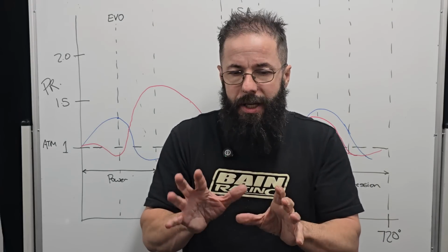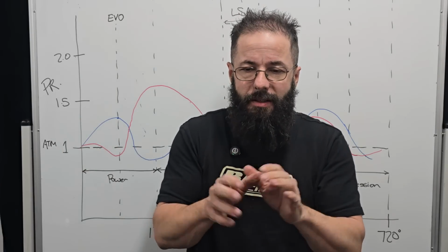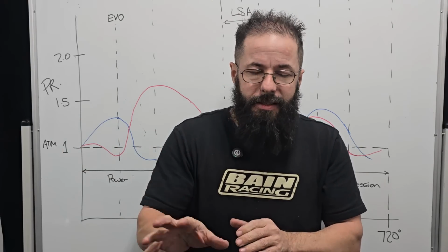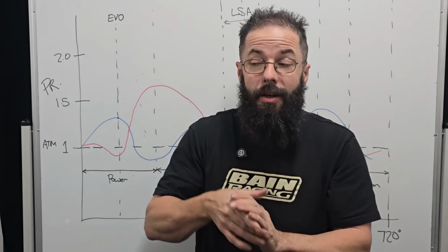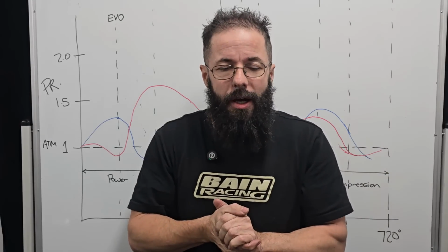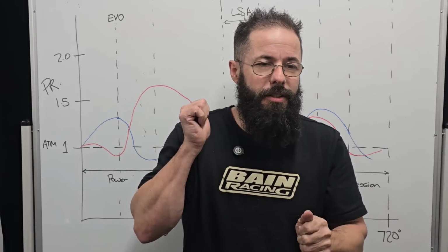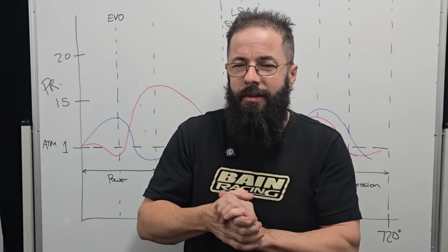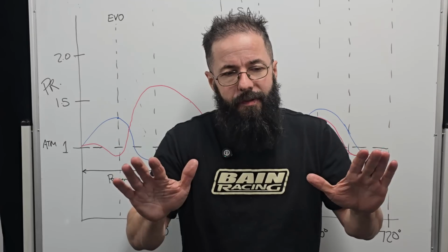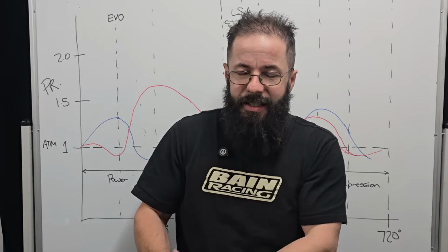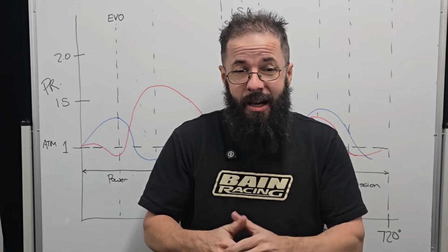we would put a combo together, and I was doing street combos and different bits and pieces, and we actually did one for Frank's big block, and on the analysis it came up at like 626 horsepower, and we put this thing on actually Sid's dyno, of all dynos, and it was pretty good dyno. And I think with a couple of jet changes, and I think the second pull, it went 627 horsepower after I'd had an absolute nightmare fight with the exhaust guy who had paired cylinders wrong, and this engine wasn't making horsepower, and the customer's at me going, Jake, what have you done?